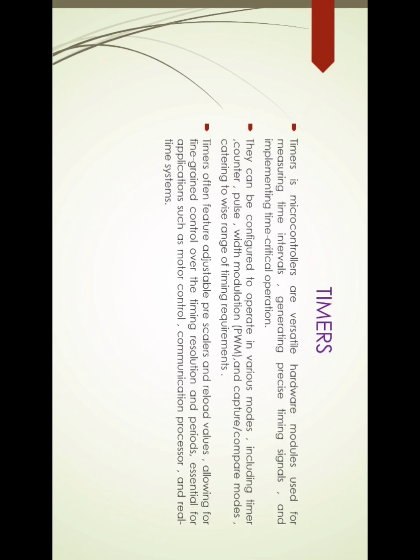Timers. Timers in microcontrollers are versatile hardware modules used for measuring time intervals, generating precise timing signals, and implementing time-critical operations. They can be configured in various modes, including timer counter, pulse width modulation, PWM, and capture or compare modes, catering to a wide range of timing requirements.